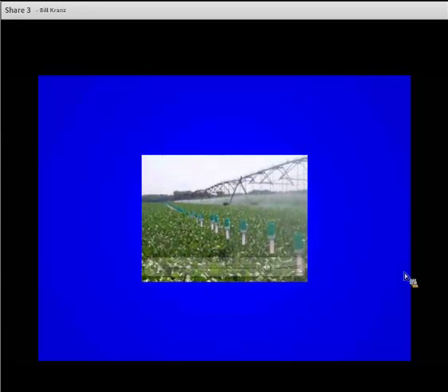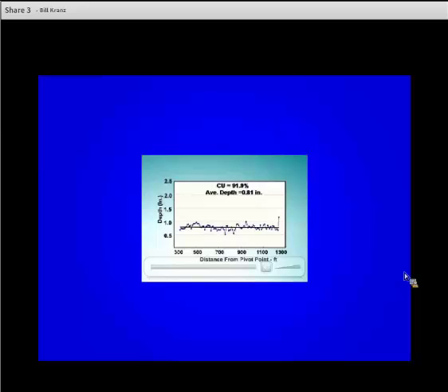This was supposed to be another video that I'll try to talk you through as we go through this. We look at water application uniformity, that we really should be above 90%, and there are different ways of doing the catch can test. This happened to be one from Kansas State, where we've got some printouts, and the first image that you're seeing here is one that has a fairly high coefficient of uniformity, and if you actually do those, you'll see that there's variation in those numbers over time.